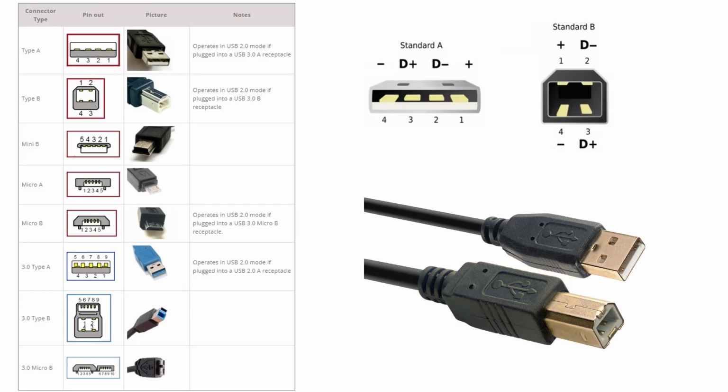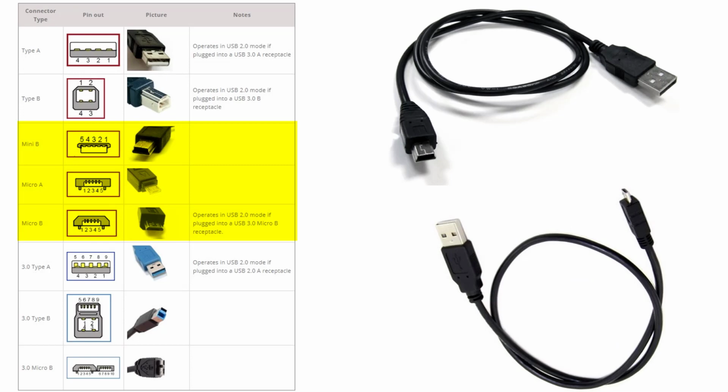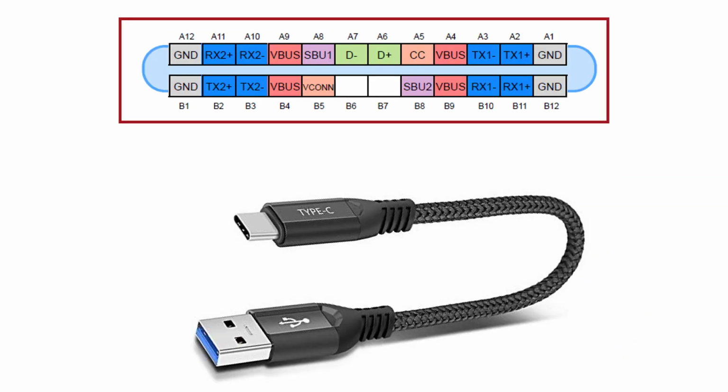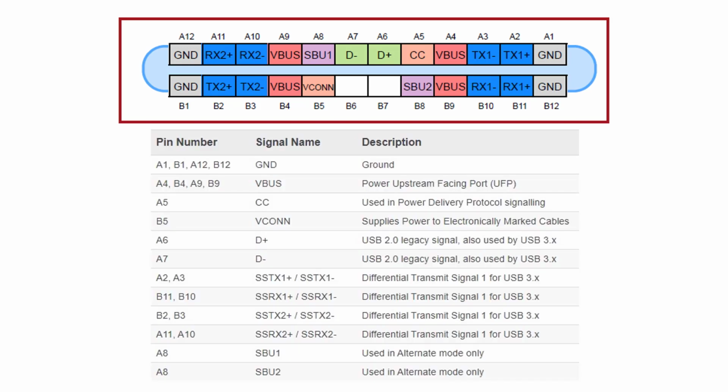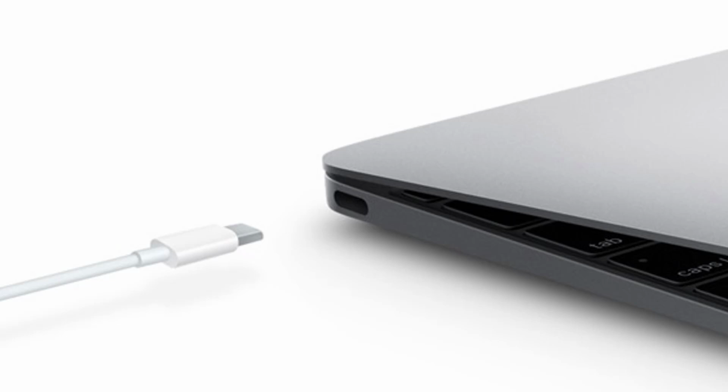There are also smaller connectors to reduce the size of the connectors. They are USB mini and USB micro connectors. The USB Type-C packs 24 pins into the USB connector. Unlike the previous versions, this version is reversible, meaning the USB connector can be inserted either way. There is basically no wrong way you can plug a USB Type-C cable. This allows also for current above 500 mA for your device. But depending upon the mode of operation, all of the signals may not be needed. This new Type-C is becoming the standard for many new devices like laptops and phones.